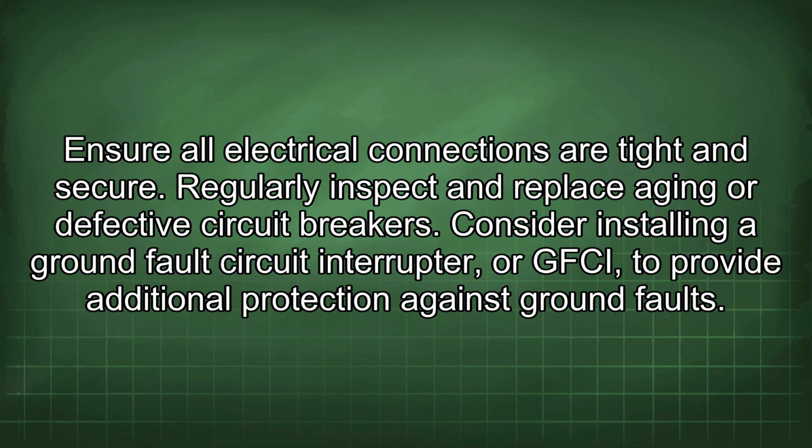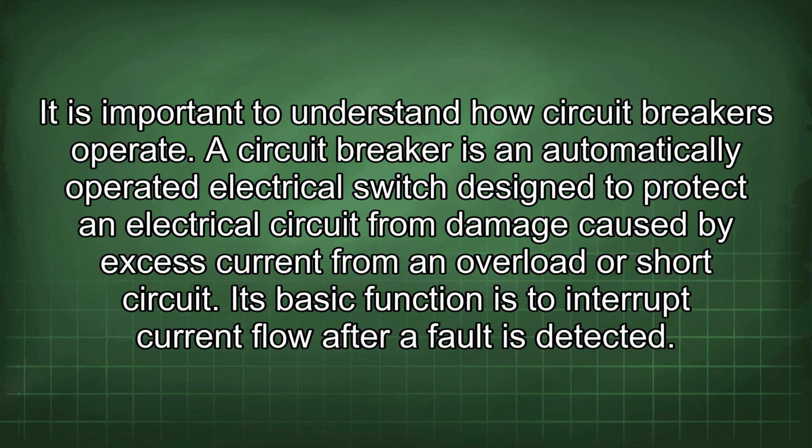Ensure all electrical connections are tight and secure. Regularly inspect and replace aging or defective circuit breakers. Consider installing a ground fault circuit interrupter, or GFCI, to provide additional protection against ground faults. It is important to understand how circuit breakers operate.